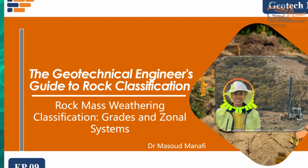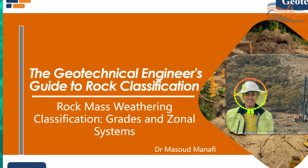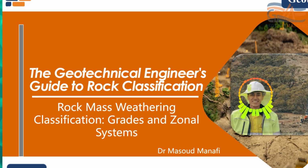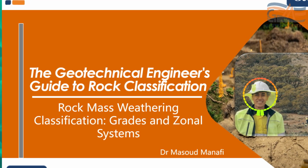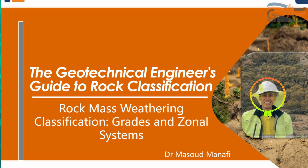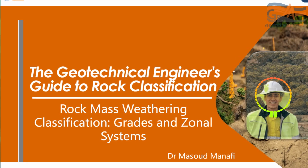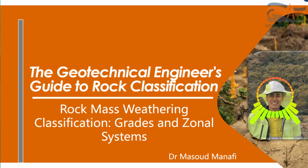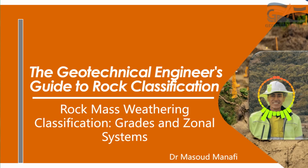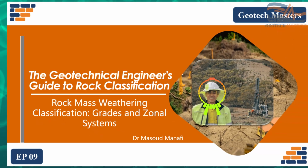In this episode, we'll learn how to classify the entire ground profile using a standardized 6-grade system. We'll move from grade 0, which is fresh rock, all the way to grade 5, which is residual soil. This system helps us understand how the ground changes from the surface down to the solid bedrock. Let's explore these together.